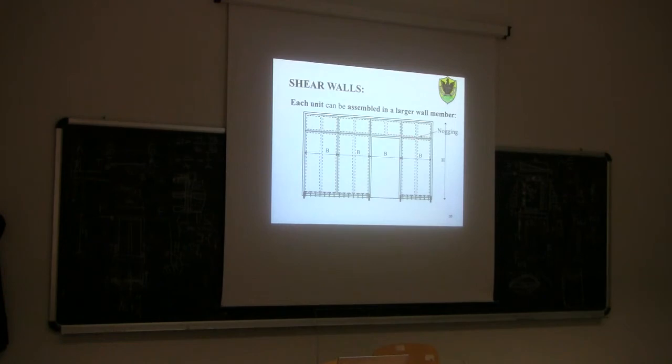So this member here basically is not stressed at all. This member is mostly there just to get this continuity of shear flow between this sheeting and the sheeting underneath. It's just needed in order to get the nailing of the two sheetings across this timber member.